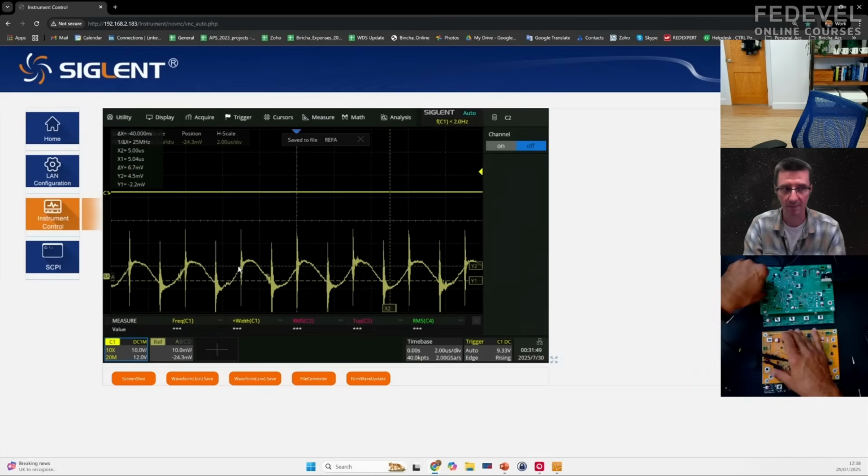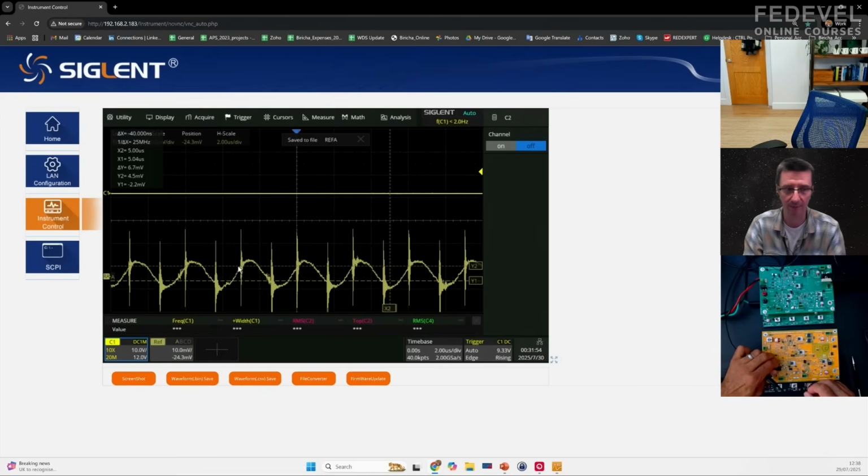I'm curious. So this is basically why we have to use two different calculations for ceramic and electrolytic, because even on these waveforms, we can see they behave differently. Yes. And it's a bit confusing because when you're looking for equations in textbooks and so on, you get 3 different equations and you don't know which one is right. But the answer is all 3 of them are right. One of them is for dip, one of them is for ripple if you're using ceramic capacitors, and another one is for ripple if you're using electrolytics.